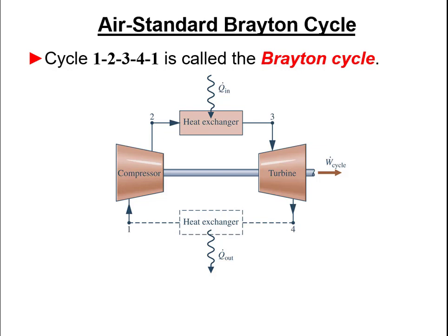When we think about how to do a Brayton cycle problem, it's a bit of a combination between a Rankine cycle problem and an Otto or diesel cycle problem. It's a little bit like a Rankine cycle because we have multiple different components in our cycle and we treat them as open systems. So we'll be using the open system version of the first law. But it's a little bit like an internal combustion engine problem because we're going to assume that the working fluid is air. So when we start to fix our states, we'll use some of the same methods that you'd see in an internal combustion engine problem.